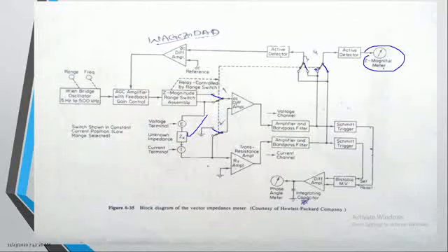And here the operations are reversed. The DC operational amplifier output is used for controlling this particular element, and again the same explanation. The Schmitt trigger is the one which translates our sinusoidal waveform into the square waveform, measures the phase difference between them, and displays whether it is capacitive or inductive in nature.